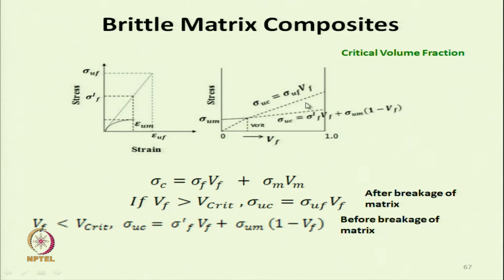So, it is ultimate stress of fiber multiplied by volume fraction, that will be the ultimate stress of composite.